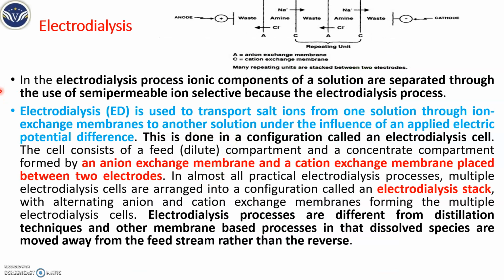In the electrodialysis process, we use a semi-permeable membrane and introduce cations and anions. We put in different charges, and here there is an ion exchange membrane. An electrical potential difference is added, and it attracts the opposite charge. By doing so, we remove the impurities.